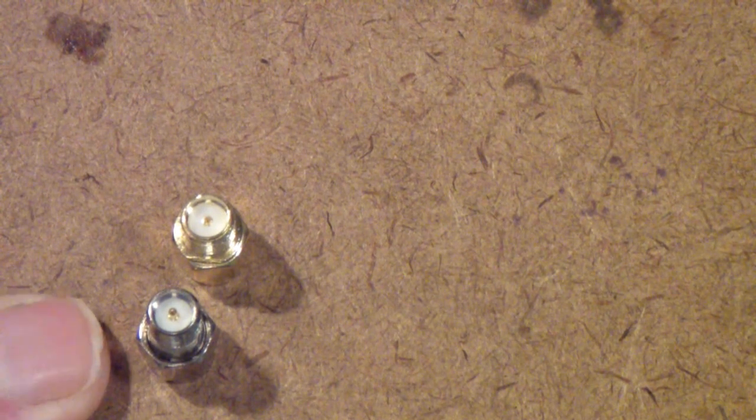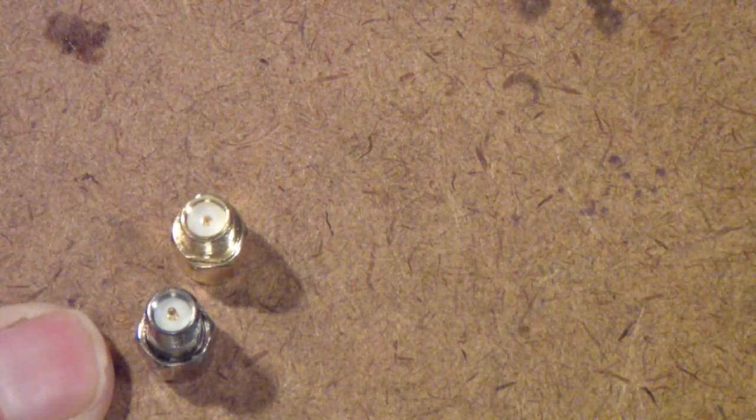Well, of course, it didn't take long until lots of people were making reverse polarity SMA connectors and antennas with reverse polarity. And so, like anything, when you try to stop people from doing something, you invariably encourage them to do it. And that's what happened in this case. So today, even though the FCC no longer is pushing router manufacturers to use reverse polarity connectors, that has become such a standard that most routers today have reverse polarity antenna connectors.